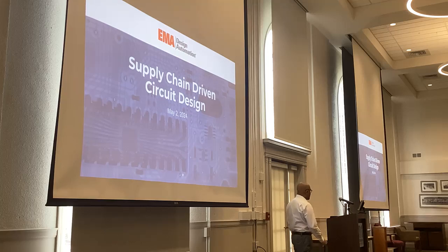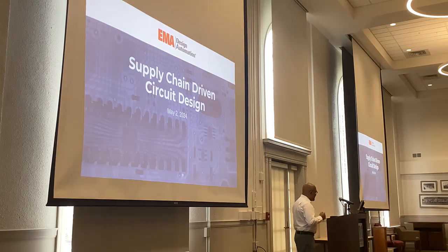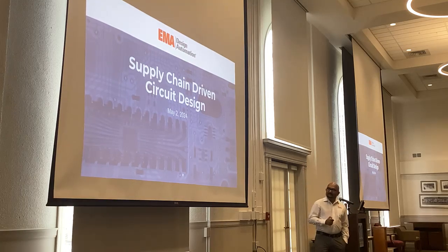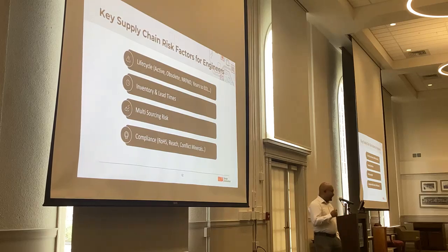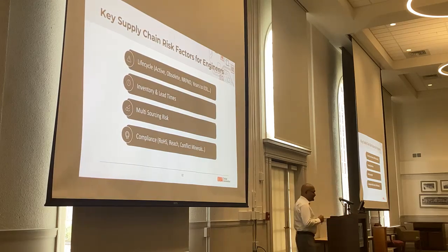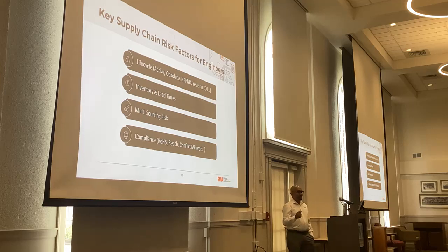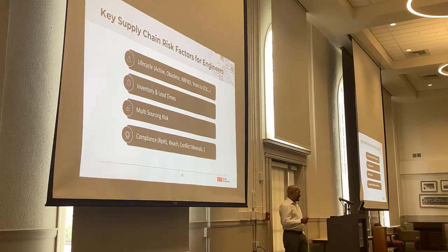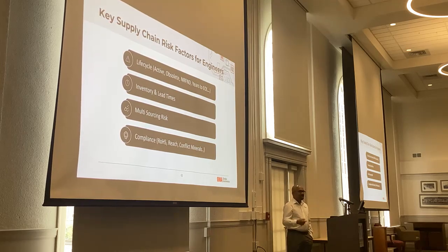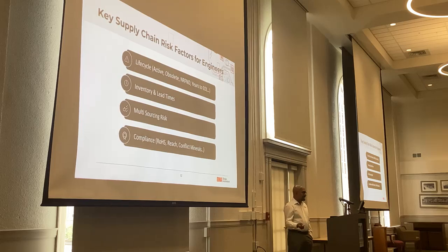So we're going to talk about supply chain driven circuit design. So what are the things that we care about when we say supply chain, because it's such a broad term, right? So the most important ones here are lifecycle, right? So when you use components on your design, you want to find out if the parts are active, obsolete, not recommended for your designs, and so on.